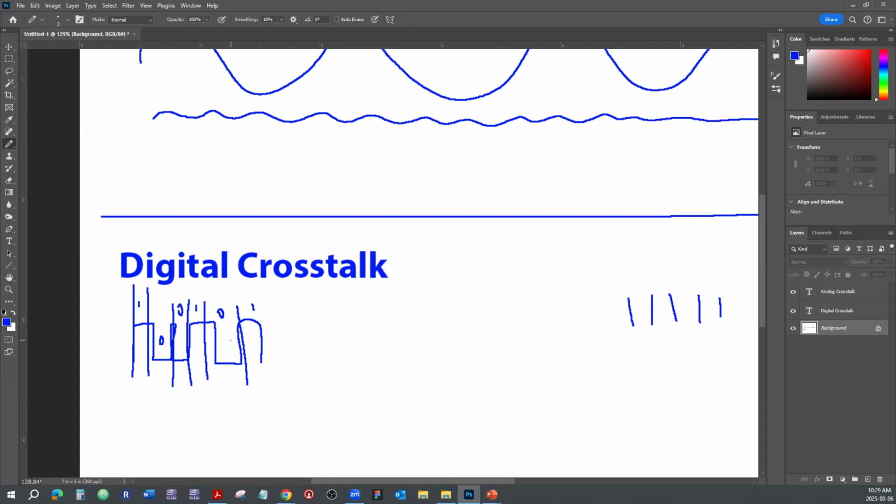So at the beginning of a transmission, the transmitter is going to say, "and now." The "and now" is going to travel and get to the receiver, and the receiver is going to say, "and now." It's going to start reading at the same speed that this is being transmitted. It's called baud rate.